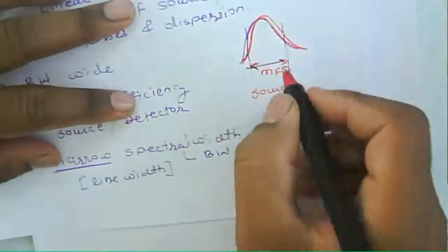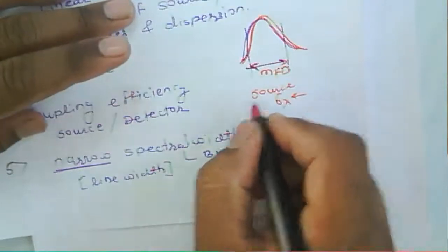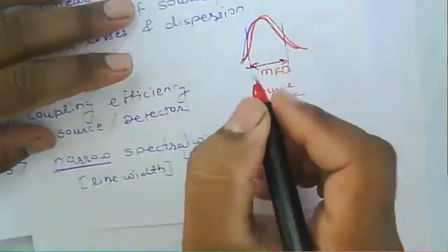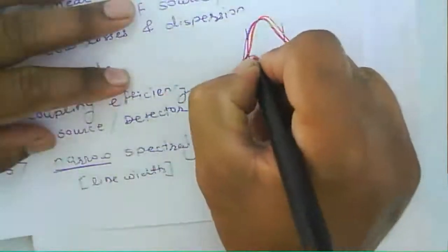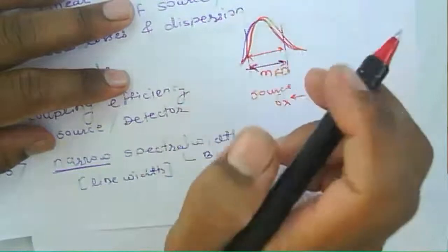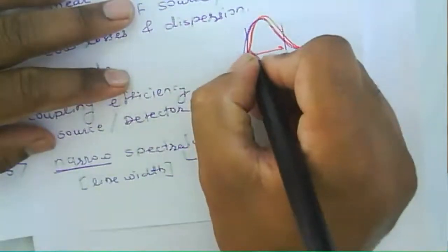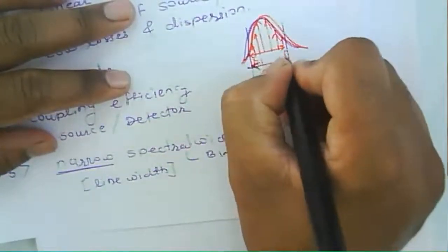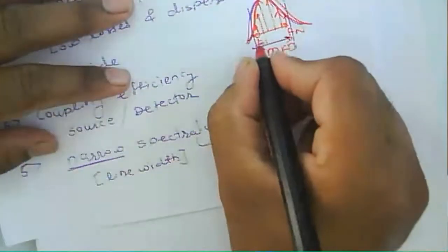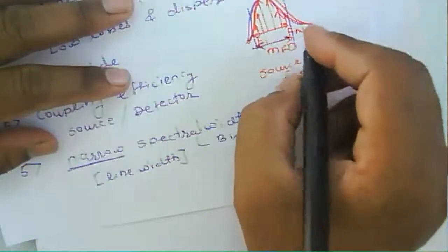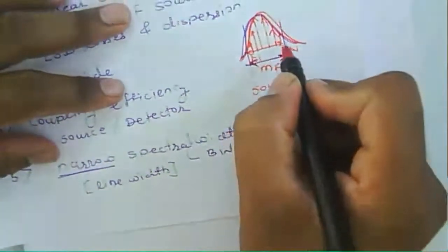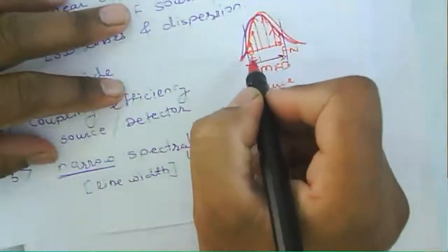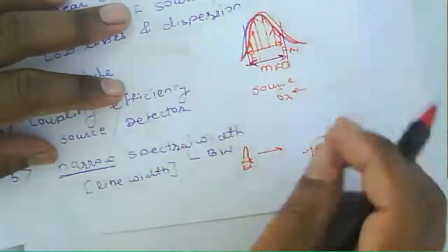Now in the case of a source that has a spectral width, we are expecting it to be a narrow one. So if that spectral width is narrow, then the spectral components for the given particular range will be small. Generally a source emits light that has various spectral components, with frequencies f1 to fn. Now from the frequency f1 to fn, each frequency component propagates through the fiber, the last frequency component comes first at the detector, and the first comes later. So that's why the dispersion occurs.